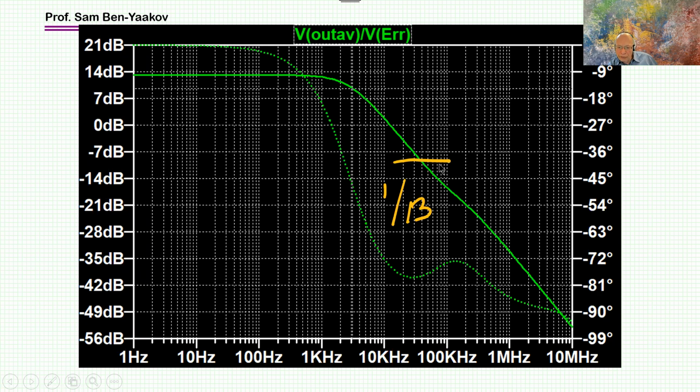This is a bit close. I might have gone actually lower because it's a bit close. Once you get close to the switching frequency, you have phenomena of sampling, and you can have oscillation, which are more in the digital or sampling domain, and you cannot explain them in a small signal transfer function, okay?